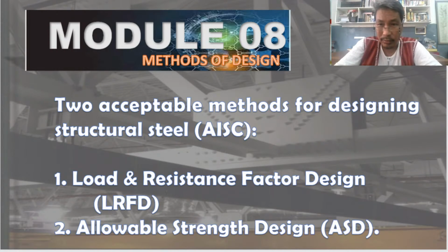This is not the only author that uses this terminology. Anyway, we are referring without confusion to a certain method which is called ASD. They define it sometimes as allowable stress design, sometimes allowable strength design, but because of the word allowable, it is different from strength design. Take note of that. You may get confused when there are problem solving or questions about strength design and allowable strength design.